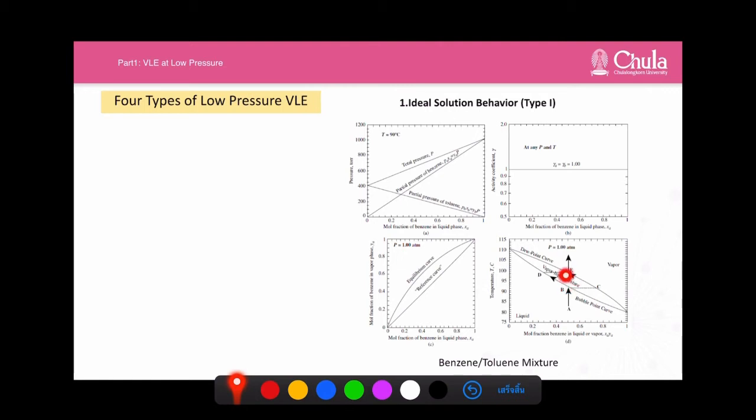And you see that in this temperature range, we induce our solution to separate into a liquid phase and a vapor phase, and you know the composition of each phase at each temperature. So you can adjust, right? And we obtain a vapor phase and a liquid phase with different composition compared to the original one.